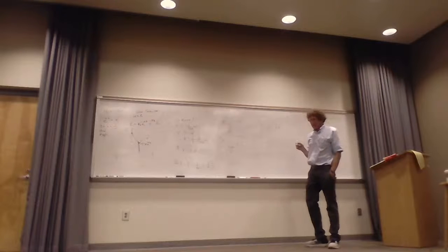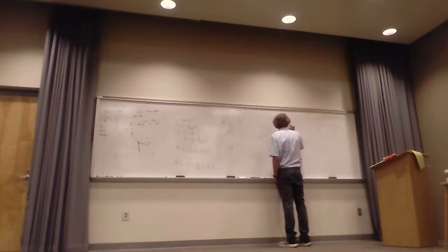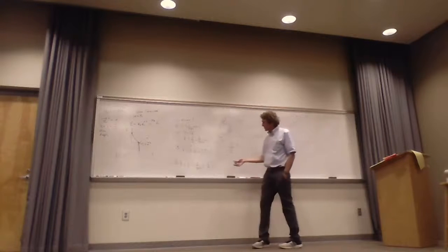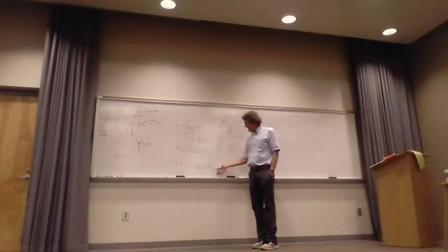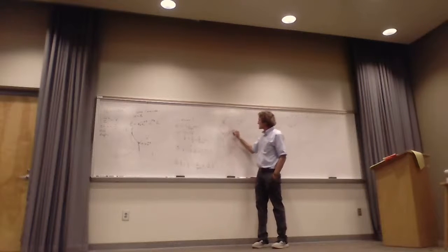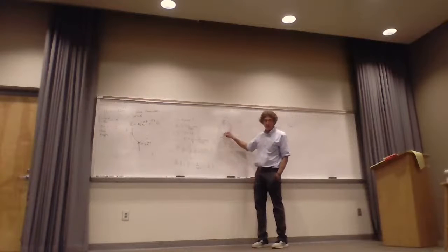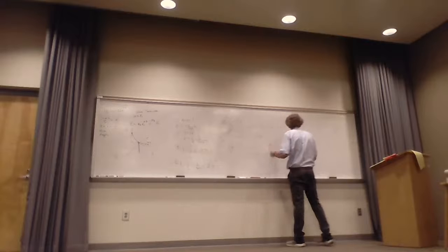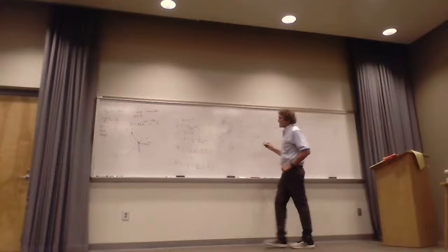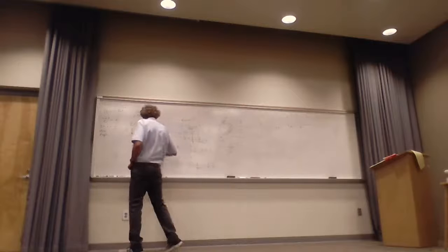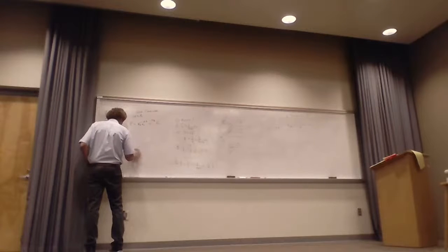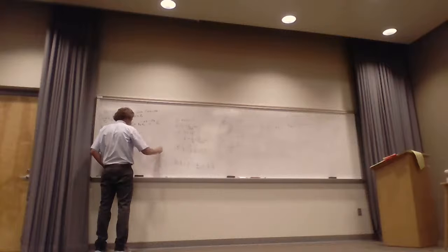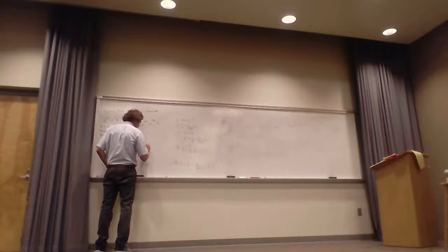If that's the case, then the actual resistance, this will be an AC resistance, will be equal to, it'll still be proportional to length, but the area now will only be this annular ring. You all see that? So it's still proportional to length, still inversely proportional to sigma, but now, well, what is the area? And here's how I like to explain it. When I think about that area, try to do this. I say that we're looking right down the cross-sectional wire.